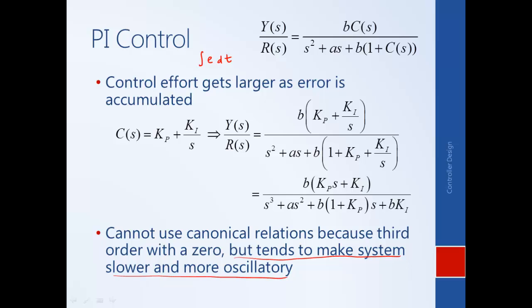One reason for that, maybe you can imagine, is in order for the effect of the integrator to take hold, you need to sum up the effect of the error. So if we imagine our error doing something like this, in order for the effect to build up, we need to add up the area under the curve. But if the error switches sign, then the direction that the controller is pushing doesn't necessarily change sign.